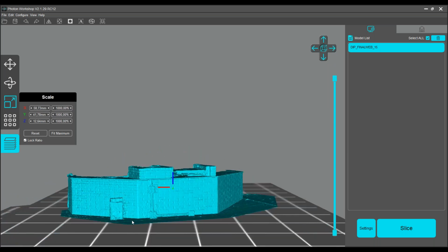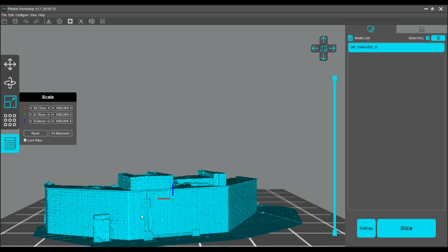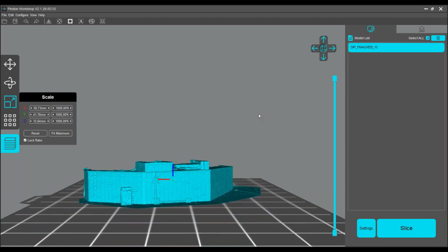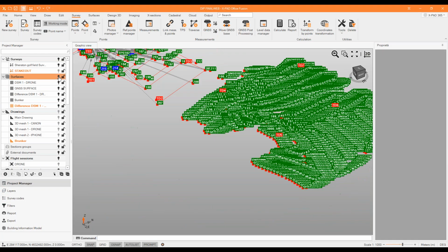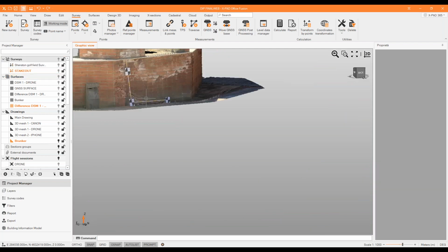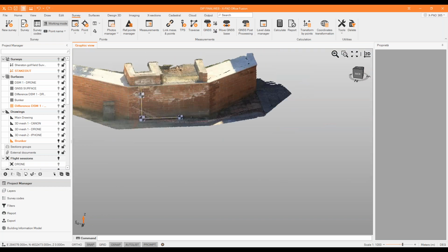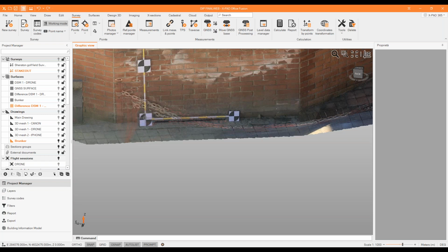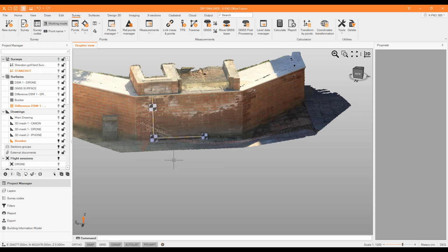So as you can see there, we have the grill. This is the external grid. This is the wooden meter plus the target used to scale the project. I will directly show you the result here. So grill bar plus also target used. So 1 meter and 60 centimeter difference in order to create 3 points and scale the project.